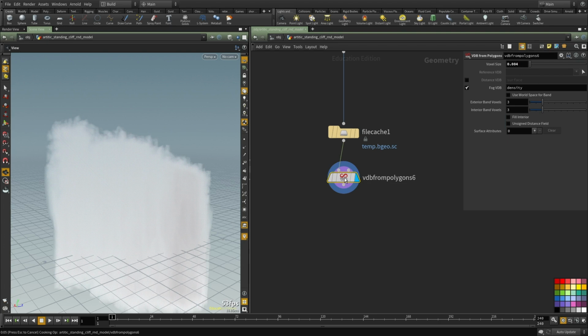When we did the copy, there's a lot of pieces interpenetrating together. There's a lot of interior faces and stuff, and all the geometry we don't need. So by doing a volume of all of that and then combining that together and converting it, we're going to leave only the data that is at the shell. At the same time, we're also going to blend in everything nicely in terms of edges. We're going to seamlessly blend all of that.